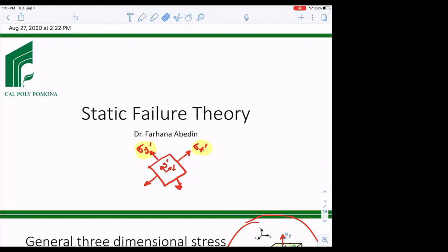Okay, so remember our goal in strength of materials was to calculate what will be the stress at various orientations, how you calculate them. But for machine design, we're designing something. For this case, our goal is to be able to come to a conclusion whether the structure is going to fail or not. So we are a lot interested in either maximum shear stress or maximum normal stress. If you're dealing with maximum normal stress, that's the principal stress.